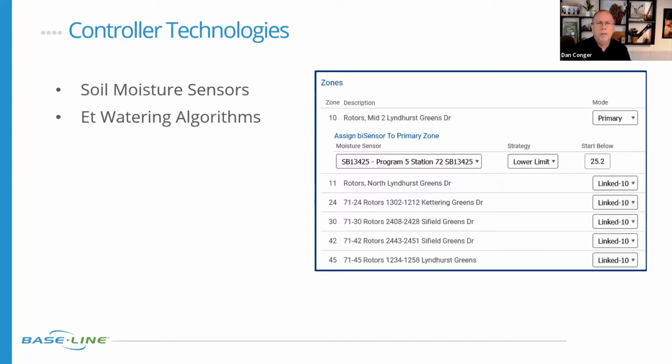So Andy, what's the difference if you just took as soon as it started raining and you just stopped instead of pausing? Why wouldn't you just go straight into a stop condition? It might only rain just a fraction of an inch. Yeah, right. And then it's done. And then you go right back to high ET again. The sun comes out, it's hot, and the moisture starts to go down again.